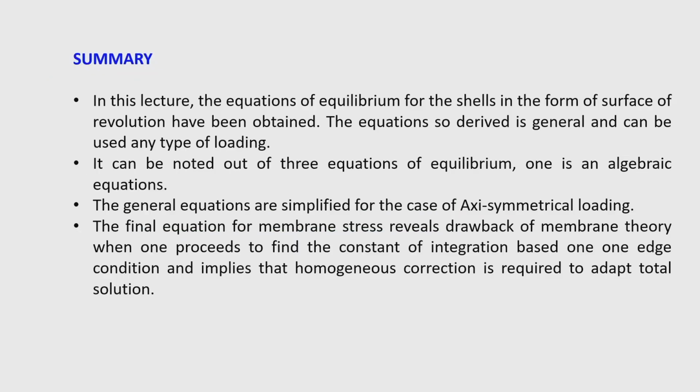So, today what we have done? We have discussed the equations of equilibrium for the shells in the form of surface of revolution, and the equations so derived are general and can be used for any type of loading. The three equations that I have derived first are general equations of equilibrium, and whether the loading is symmetrical or unsymmetrical, you can use these three equations.